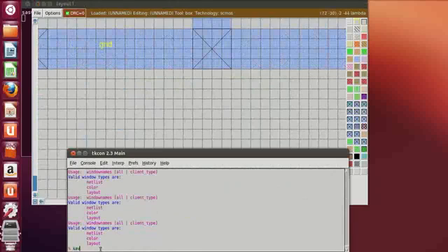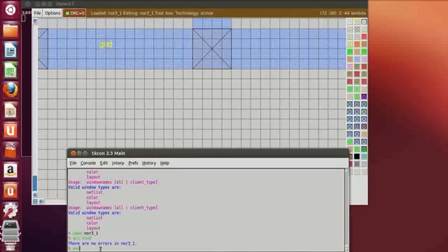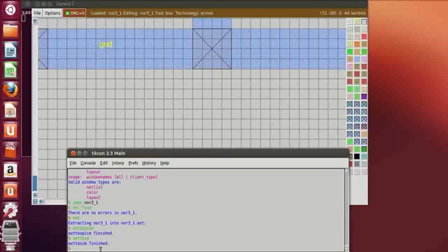Okay, now save this as NOR 3_1. Okay, now find the DRC errors. DRC find, no DRC errors. Then extract to spice, and then extract to sim. Once the sim file is extracted, then type irsim NOR3_1.sim.